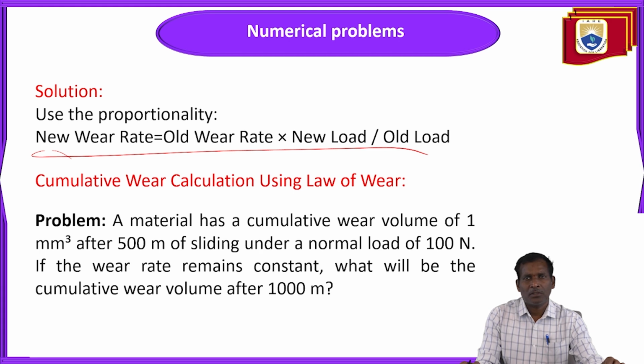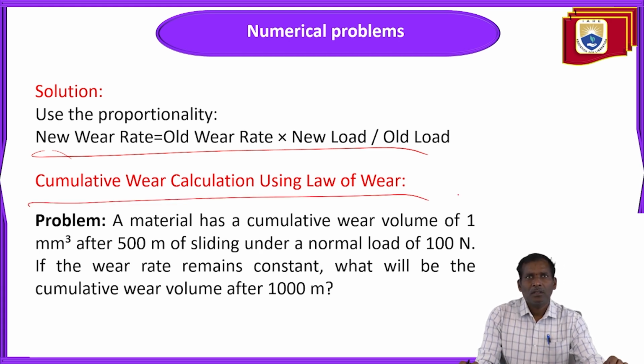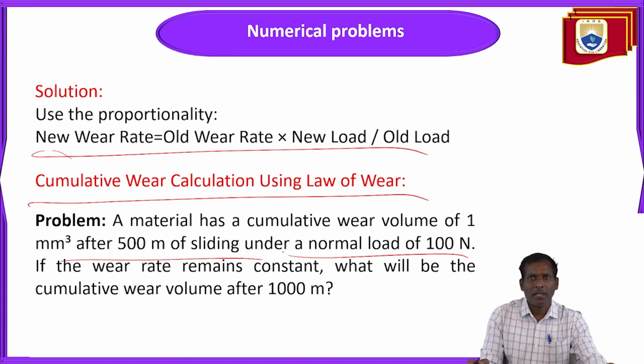Cumulative wear calculation using law of wear. A material has a cumulative wear volume of 1 mm cube after 500 meters of sliding under a normal load of 100 newtons. If the wear rate remains constant, what will be the cumulative wear volume after 1000 meters?